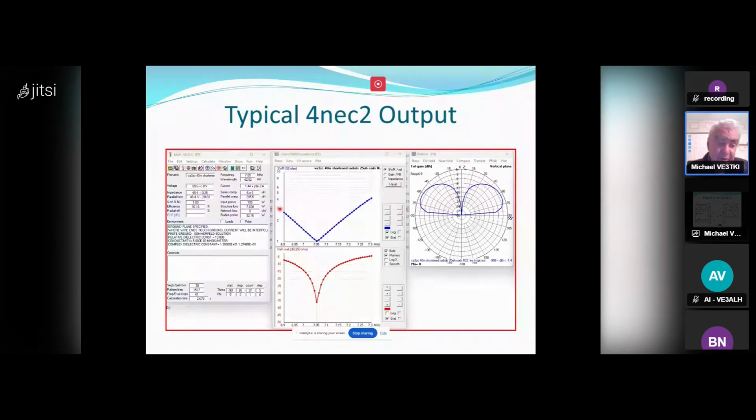This is the SWR. This is a modeled SWR, not necessarily what you actually get. And this came out with one SWR, more or less, at 1.03 at 7.05, which was my target frequency. And this is the reflection coefficient, which is pretty good at -35.